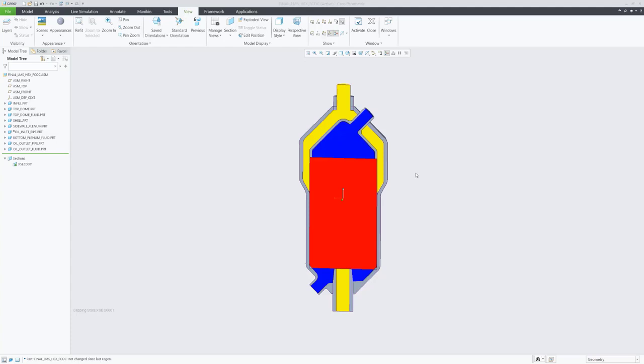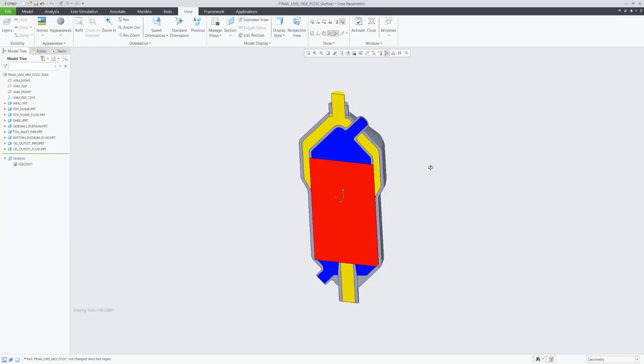The last aspect I'll touch on in our pre-nTop prep section is defeaturing. Similar to how we might defeature parts before we move into any type of FEA, we'll want to remove any unnecessary complexities that, let's say, may impact meshing and rapid design analysis downstream. We can add those back in later.